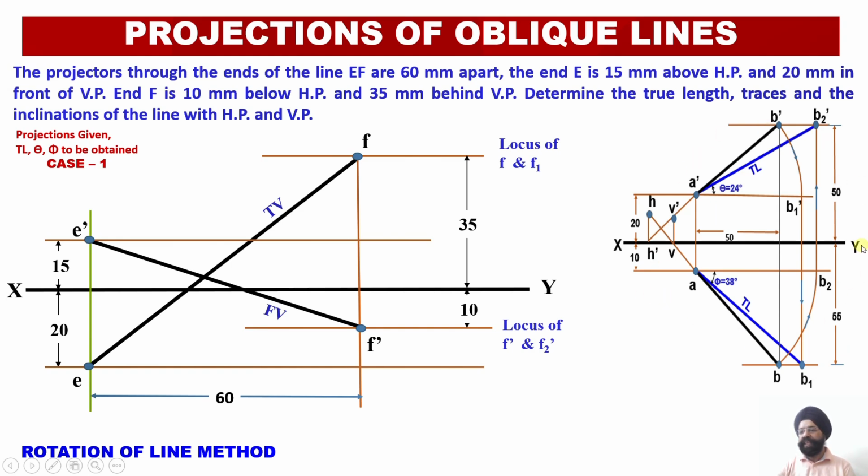So always keep this particular fundamental in your mind. I know it very well because earlier I was making a rotation on only one side and then drawing the perpendicular projection onto the other side. But once my fundamentals are clear, I know that whenever I make a rotation, I'll make my apparent length parallel to either HP, or I will rotate my projection and make it parallel to VP. That is the only thing I need to remember. Then from there, draw a perpendicular projection onto the second point of the opposite view. I'll get my true length.